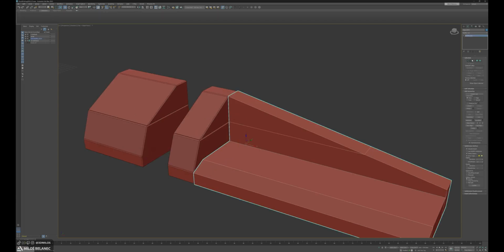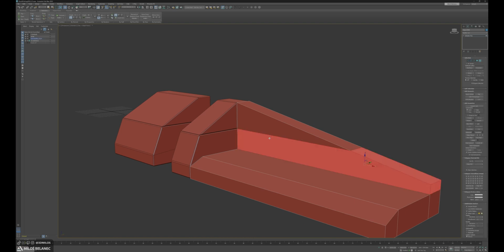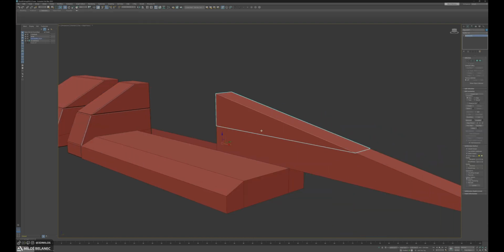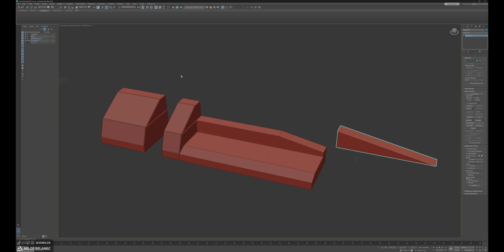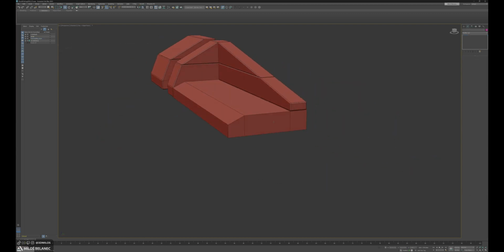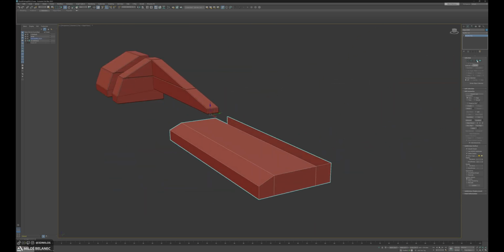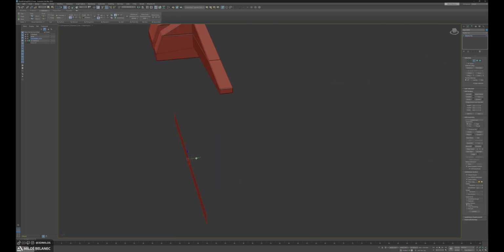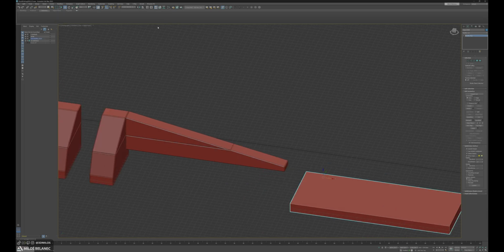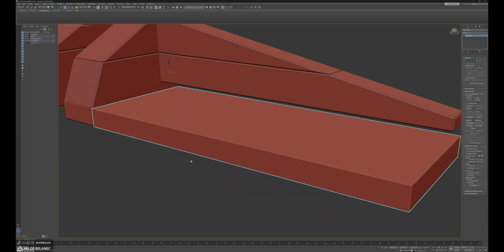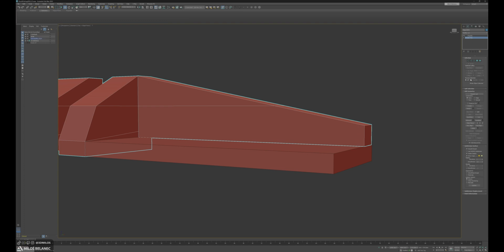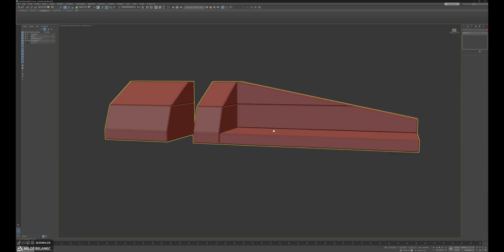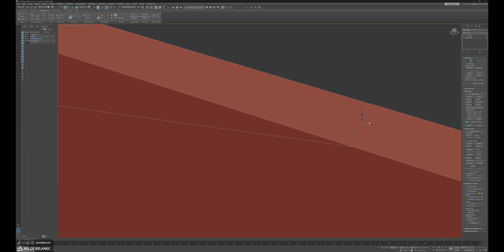And if it's a model near to the camera, or something like a hero object, yes, a model near to camera is a hero object a lot of times, it must have a different level of detail than a model in the background. For example, this model is near to the camera, but near to the camera in this scene is around 50 meters, and this is really important to know, the level of detail we need. You can spend a lot of time adding a lot of small details in the mesh, a lot of small details in the textures, but they will be lost in the distance of the camera from the mesh.